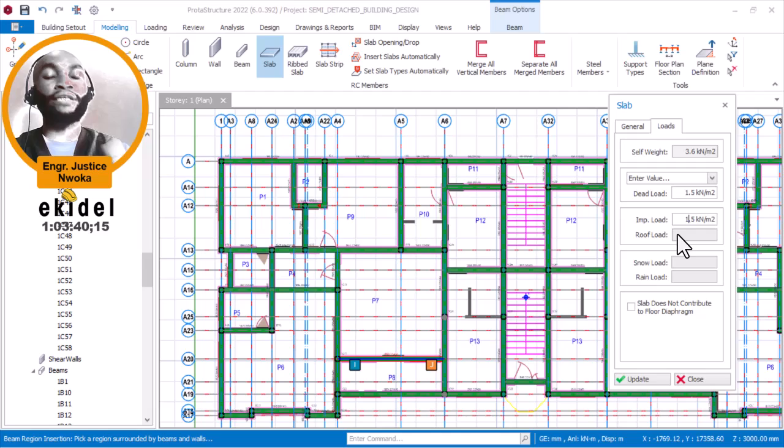That's based on experience. So I will not input anything like wind load, and since there is no snow in Nigeria, I will not input any factor for snow load. Had it been designing for countries like Canada, US, New York, I would have input a snow load of 2.44. That's the snow load in these countries which I've just mentioned.